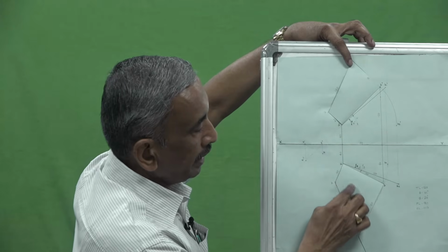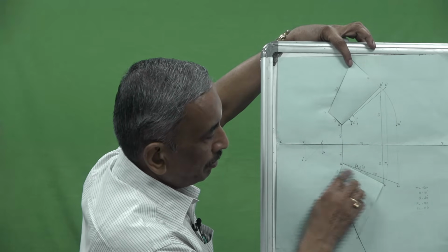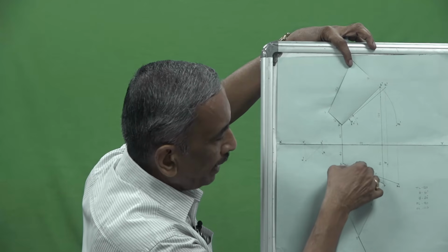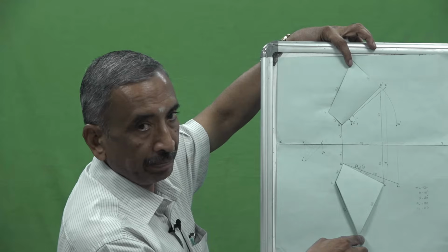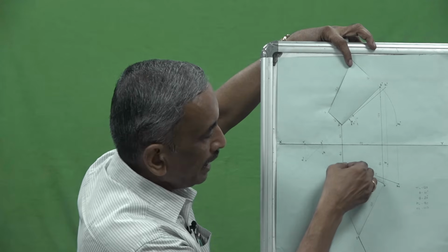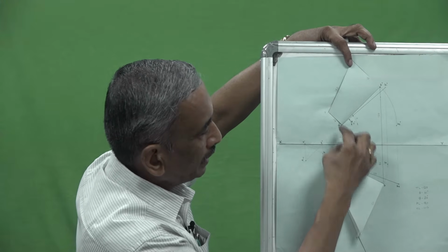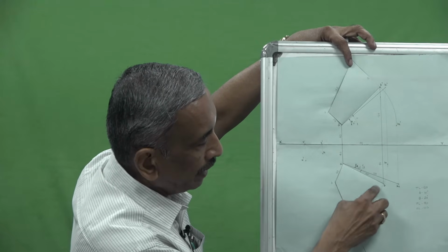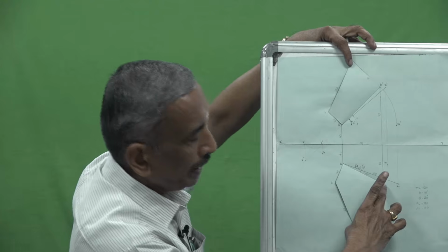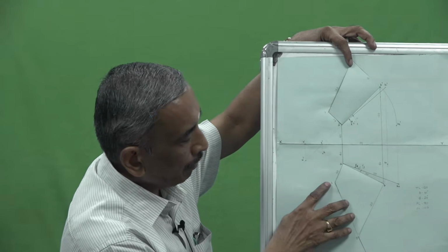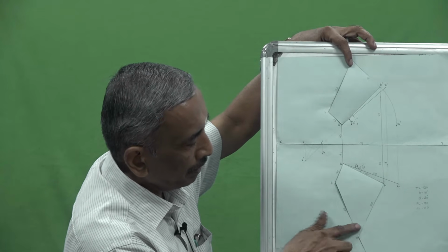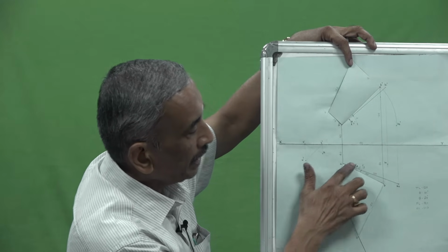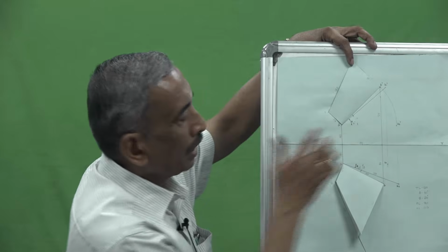Likewise, in the top view, I have the top view AB. To this line, you draw perpendicular lines through A as well as B. On the vertical line drawn through A, you measure a distance of 40 mm. On the vertical line drawn through B, you measure a distance of 120 mm. So, I will be getting this point A here, I will be getting the point B here. So, I got a trapezium here, I got a trapezium here also.